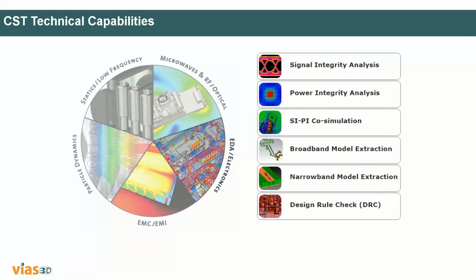You have to combine the PCB with several kinds of testing. One thing is signal integrity analysis. It is not a part of the interest of this session, but however, I tell you how important signal integrity is, which is going to tell you about crosstalk because of trace mismatches, etc. Basically, you are studying the interdisciplinary references. That is the area of interest for engineers. So it will tell you the quality of the signal you are getting when you are exciting the PCB with some kind of voltage. Similarly, power integrity analysis.